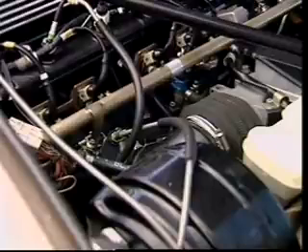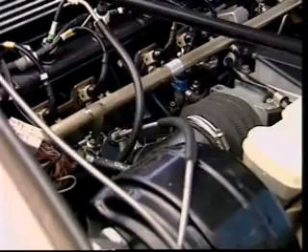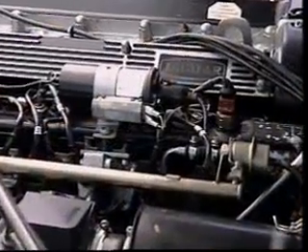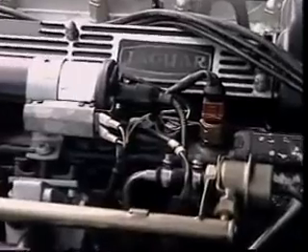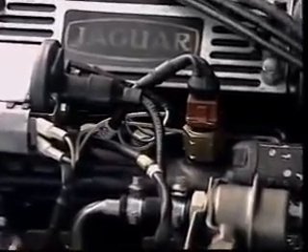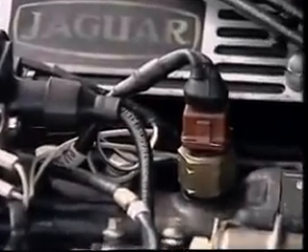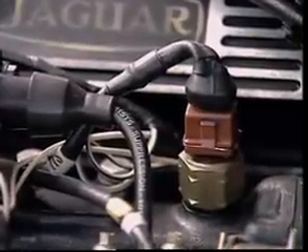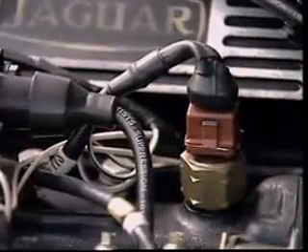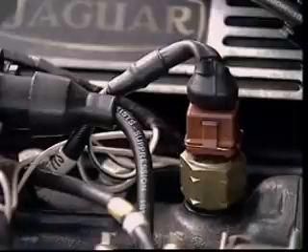Extra fuel can also come from a separate cold start injector normally mounted centrally on the plenum chamber. It's supplied with fuel under pressure from the fuel rail and only operates when the engine is cranking. A switch called a thermo-time switch immersed in engine coolant completes the electrical circuit. It controls the operation according to engine temperature. This ensures the injector operates under cranking conditions only when the engine is actually cold.